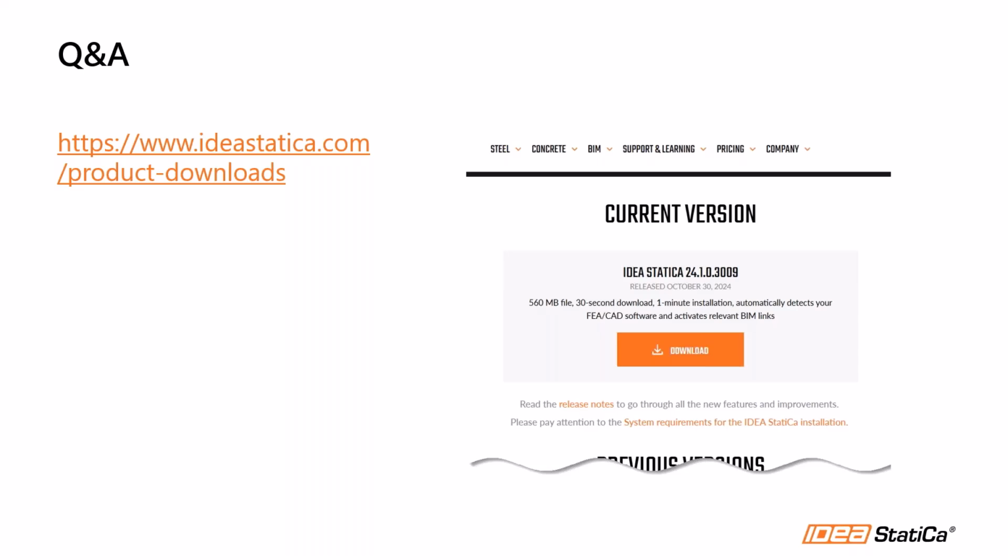You can link the parameters to different operations in the model, even for the members, so you can set up the distance, the position of the force. I highly recommend that you go to the parameter developer tab, then to the parameters, and then the linking, so you can see what can be related to what, and go to the tutorial that we have. But you can link to many different options there.